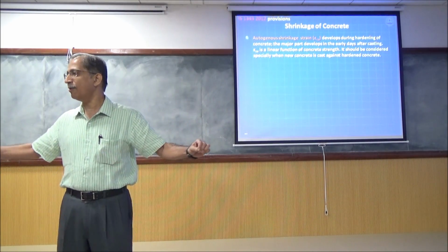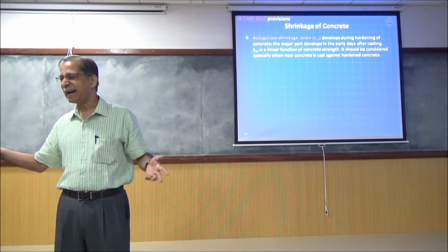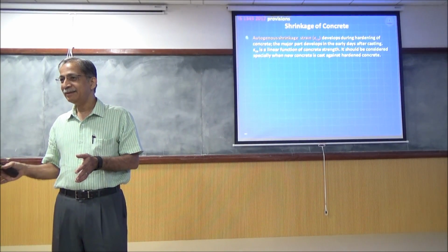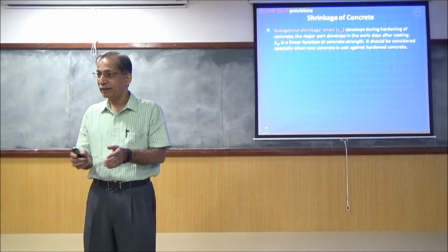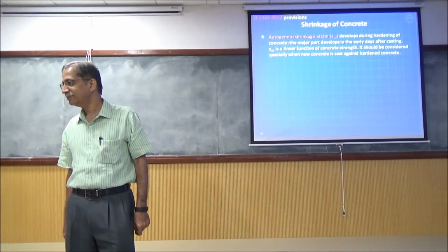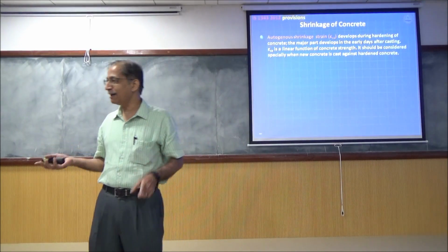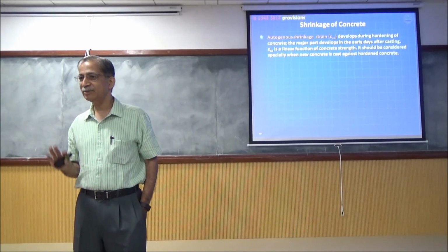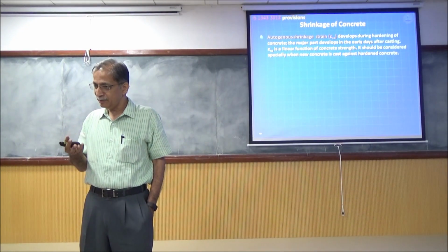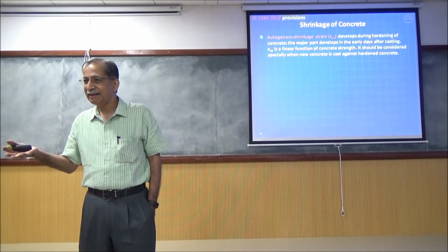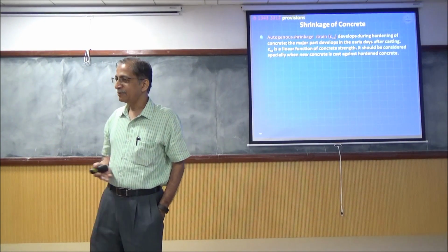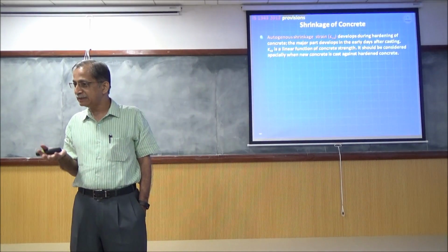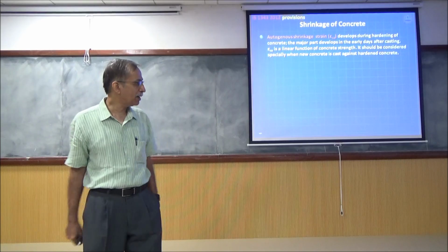Continuous means non-stop, 24/7. Practically impossible. In practice, you'll have to have breaks. But you don't forget, you come back and the break should be short. That is continual. Many practices in life can be only continual, though we would like it to be continuous. Got it? But that break is good enough. The moisture is still there, the relative humidity is high. Don't think it needs water directly. Water vapor itself is good enough for hydration.